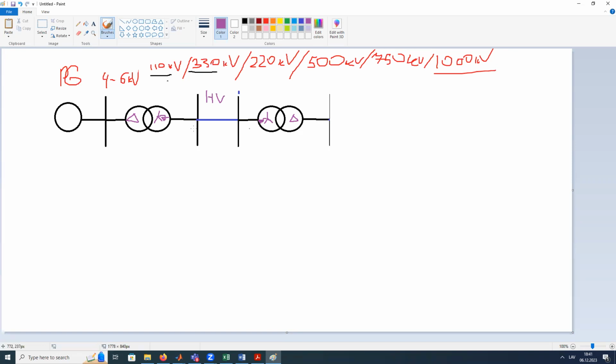If we have a delta connection, in this type we will not have a high current when we have a one phase ground fault, and we don't call it a fault. We call it a ground connection if we have a delta. Why? Because you don't have a winding connection to the ground in a delta. In this case, there is no short circuit between the windings.